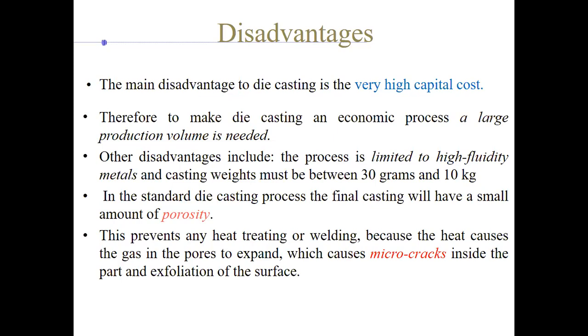In standard die casting process, the final casting will have a small amount of porosity, some kind of not so solid component, okay? A small amount of porosity. This prevents any heat treating or welding because the heat causes the gas in the pores to expand, right? Which causes micro cracks inside the part and exfoliation of the surface, right? So that heat, when given, because there is gas in the pores, porosity, that's